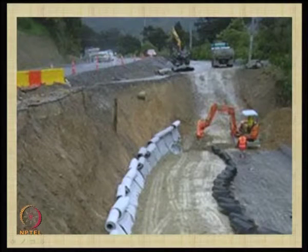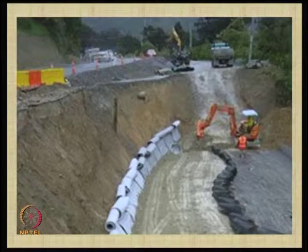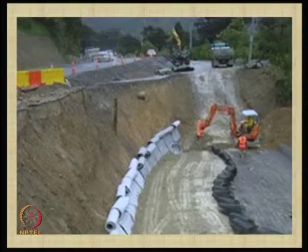Here is another typical example where you have two slopes. If the rain comes, this material is good and this material is good, but at the interface there is a possibility of a weaker layer forming. The water should not enter, and finally the new soil that you have placed should not come out. So we design properly and see that all this is taken care of by proper drainage arrangement: at the bottom and at the top all the water should go into these drains, and at the bottom you should have a collecting mechanism.